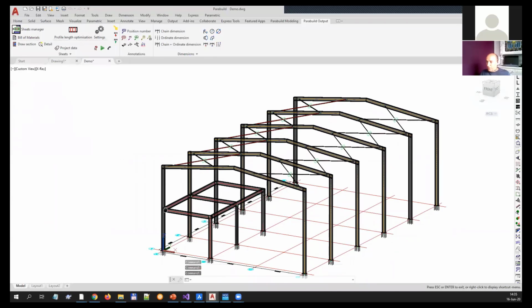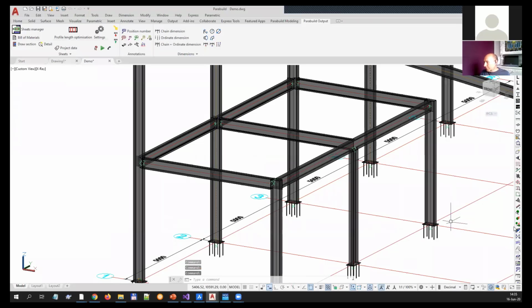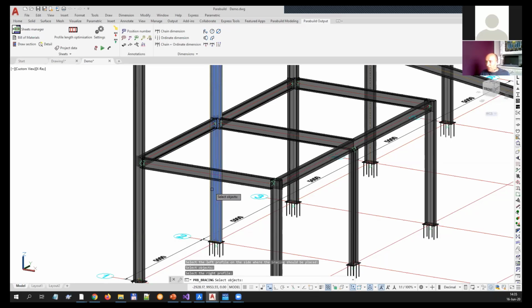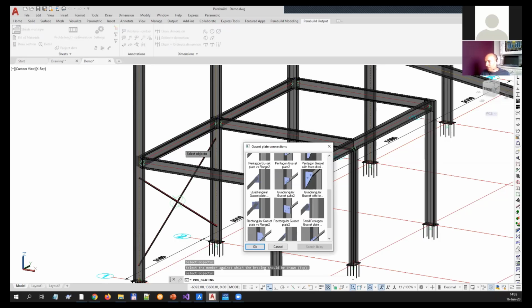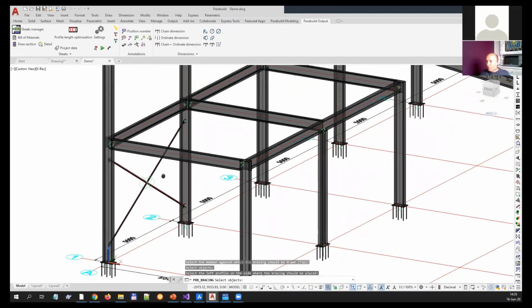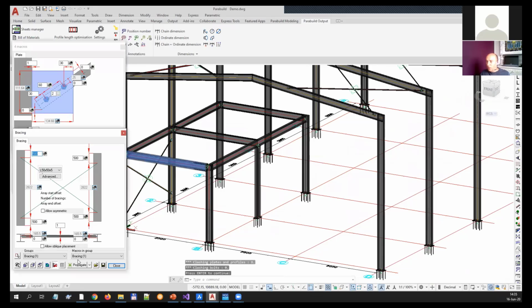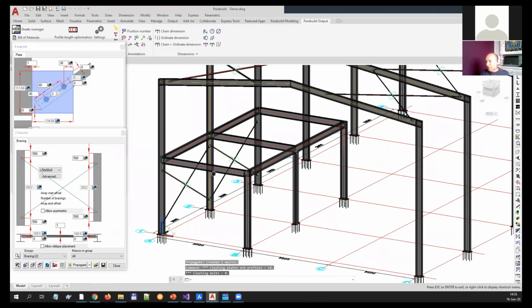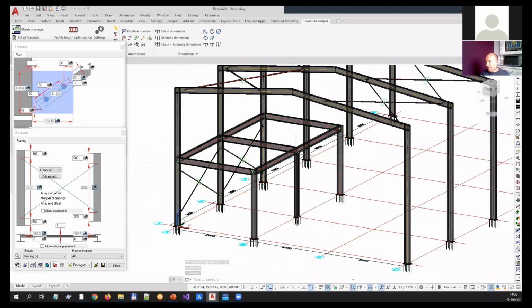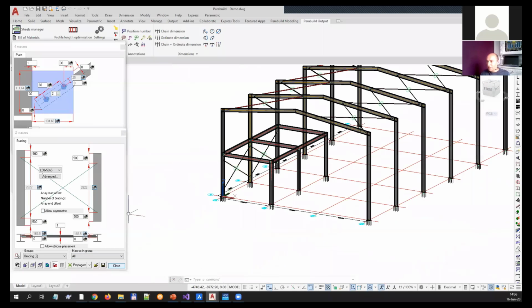Another way to draw a bracing is by limiting the extent. So what I'd like to do, I am using this tool here. I want to fix the top side to a member. So I want to draw it between these 2 columns, and I want this member to limit the height of the bracing. So that's the same as before, same tool, and I can propagate that, and that'll only propagate to the other side, because here we have this different situation. The beams, the columns are not as large at all, and we have different orientation. So that's why the propagate doesn't do the copy.